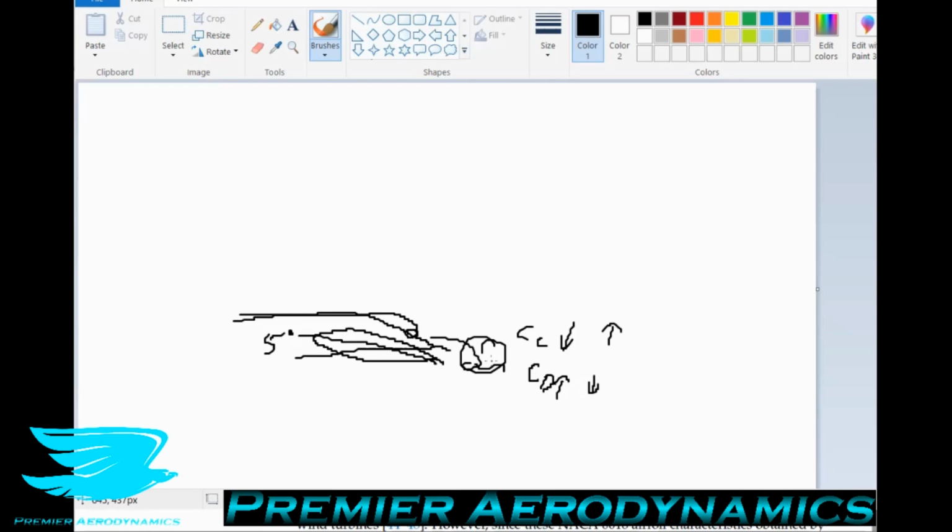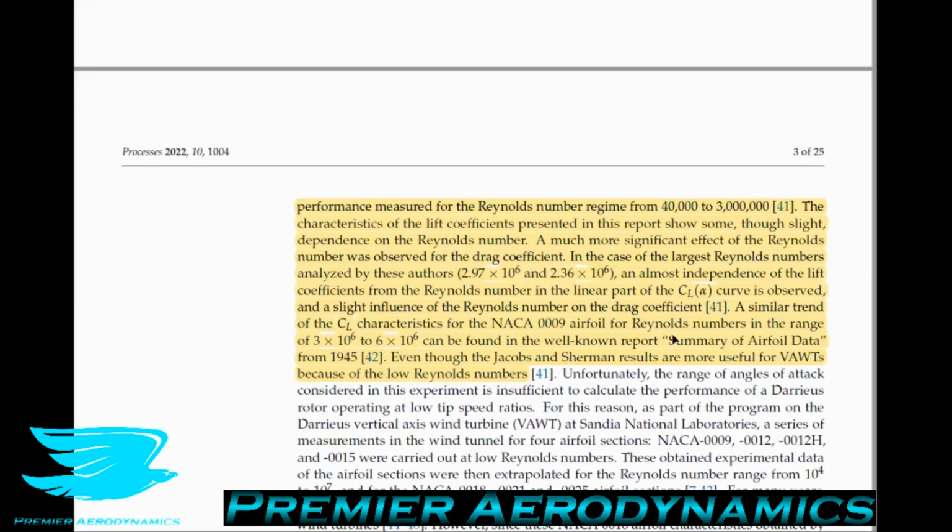As you hit a high angle of attack, this gets exacerbated. So at high angle of attack, we know that the flow over an airfoil will be more prone to stall. And if we have a high Reynolds number, it means that the flow is probably going to be moving faster and/or have more turbulence in it. So that's going to result in the velocity near the wall in the boundary layer being higher, which means that it can stay attached longer. And that means we get a smaller wake again, higher lift coefficient and lower drag coefficient. So that's what this means here.